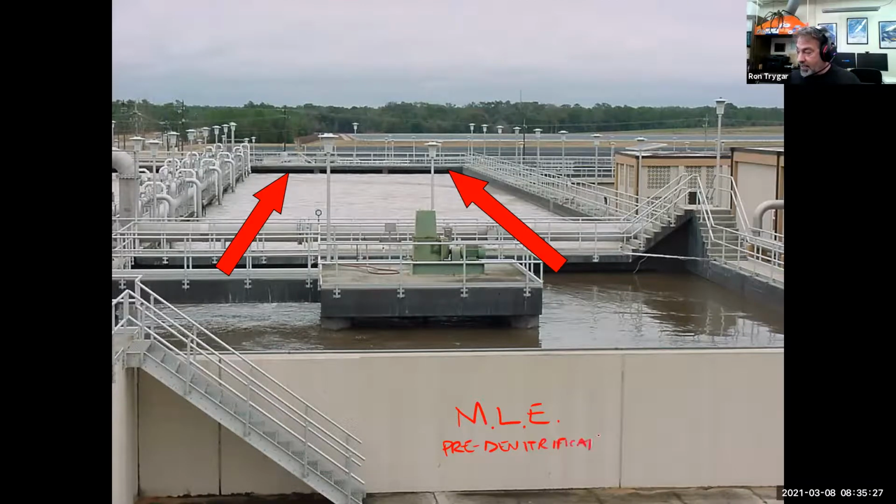nitrification. And what we're going to do is take the nitrate and present it as an oxygen supply to the bacteria in the presence of all this organic food coming in, and ask the bacteria to take the nitrate and convert it into a form known as nitrogen gas. So hopefully coming off of this into the atmosphere is N2 gas. N2 is coming off of this basin back to the atmosphere, but the flow is actually going from this basin into the aeration tank, which you can kind of see by the large red arrows there.